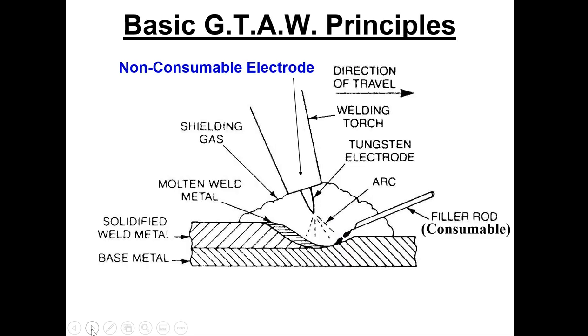So the gas tungsten arc welding process is right in front of us now. We have a tungsten, a nozzle, a filler material, an arc, a plasma cone, and a tungsten electrode that is in electrode negative, so it is able to hold this point. If you were in the wrong type of current, like AC, the sharpened tungsten, which we'll define a little later how to sharpen, wouldn't last for 2 minutes, and you'd be having to resharpen it.